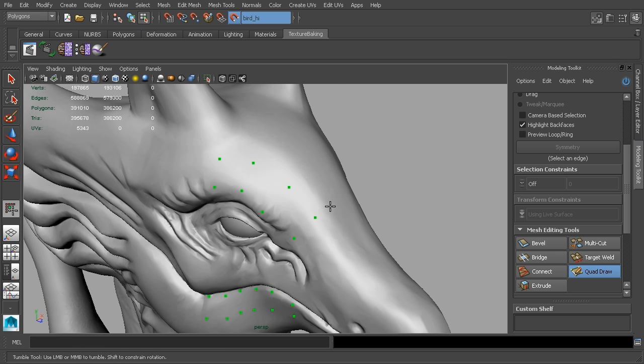Okay, so to add actual quads or four-sided polygons, we can just hold down Shift and hover between these 4 points. And you can see if I move slightly, the actual 4 points that it uses will change. So you can kind of think about the position, and if it's a little bit off, if you want those here, then you can actually start to move those around. So I can just click on those to move them around if I want them to actually connect up right there. So it's a very flexible way to work, but just holding down Shift, I can click and click through to just add those points.